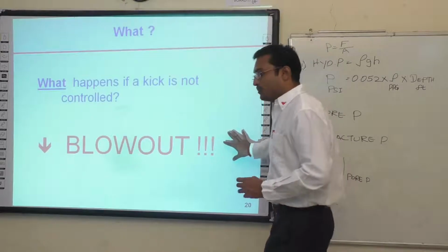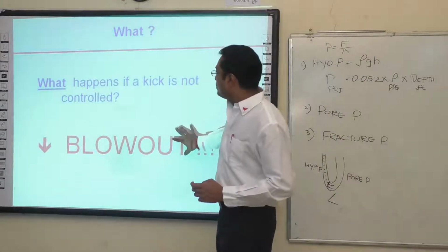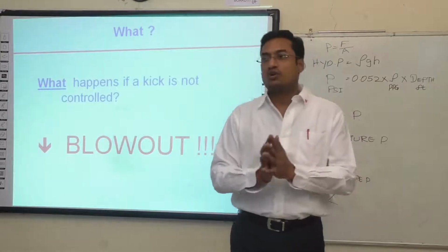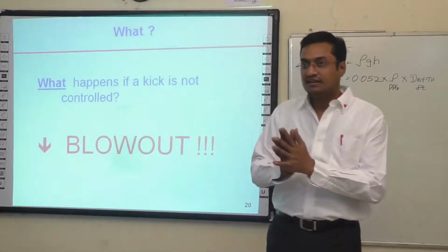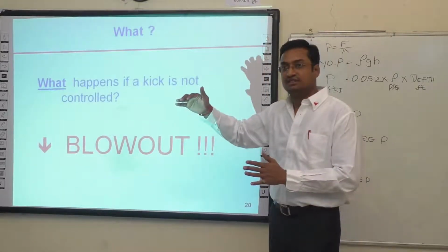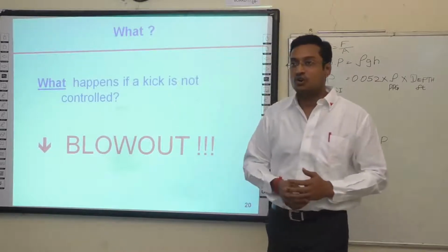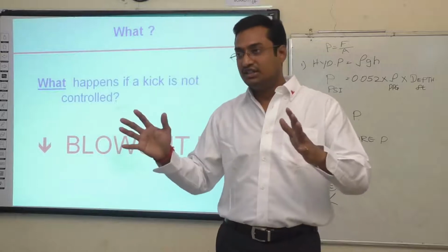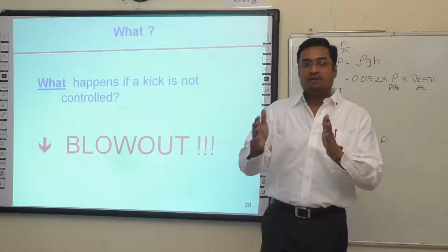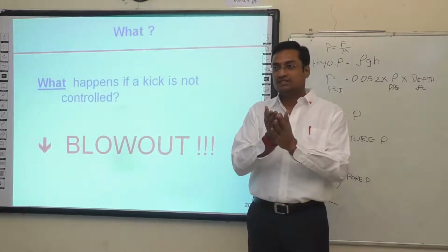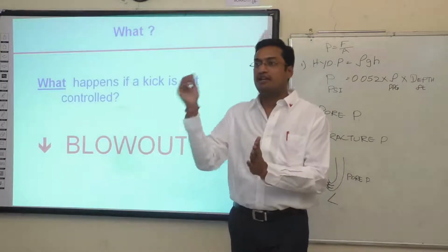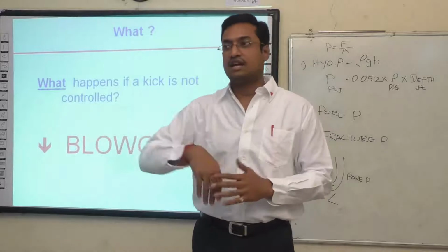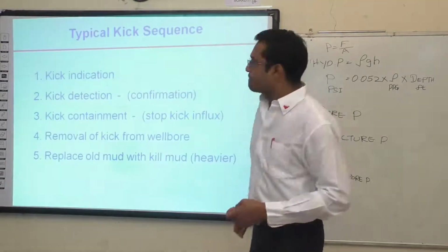So, what is a blowout? When a kick is uncontrolled, unidentified, and reaches the surface, it becomes uncontrollable and it becomes a blowout. So this is the theory behind the pressures and formation fluid entering into the wellbore. Uncontrolled, it becomes a blowout; controlled, we use kick control procedures.